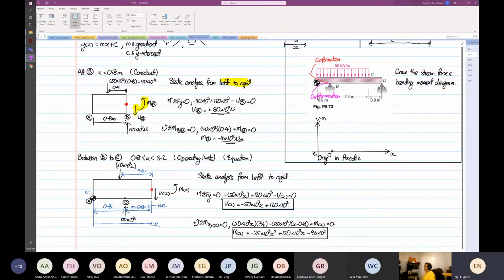Right? Okay. Usually, those of you, I know this is not a new topic to you. The only thing new to you is forming the equation. Why we form the equation is because later on we can calculate deflection. Because if you don't form the equation, you cannot solve the deflection issue. After this, we are not going to assume that the beam is a rigid body anymore. You guys remember we used to assume that the beam is a rigid body, that the beam will deflect in a straight line. After this, we are going to integrate 2 more times to find the deflection.